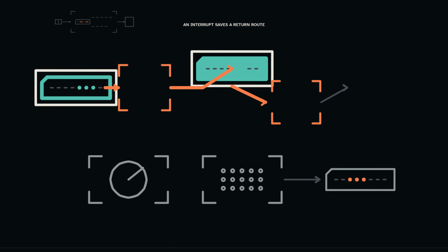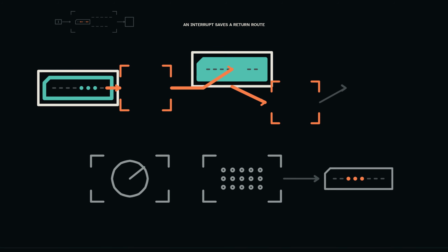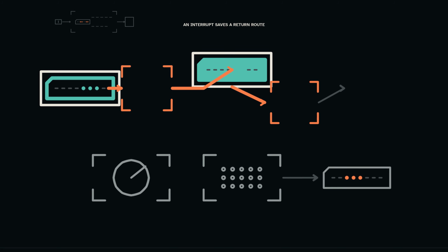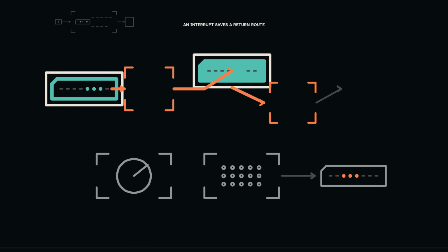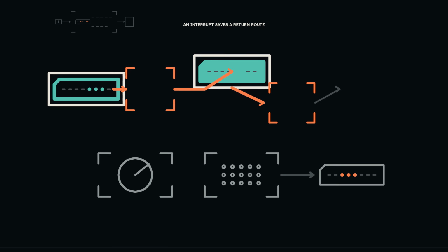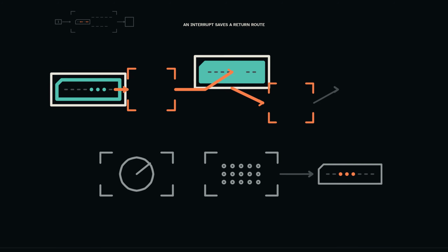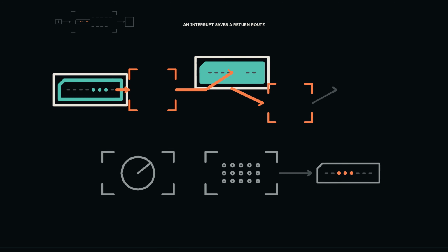Predict the necessary state changes. The processor is about to continue at address 40. A device request is accepted. Before the handler begins, what must remain recoverable? At minimum, the interrupted continuation and whatever architectural state the interrupt contract says the handler may disturb.